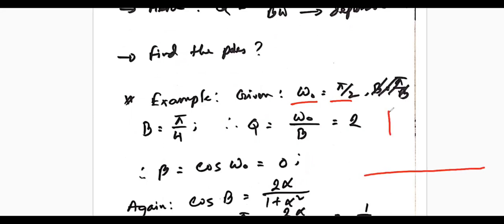So if we draw the frequency spectrum, the magnitude response plot, we have 0 here and we have pi there. And if this is pi by 2 and this is your omega 0, that means this is the center frequency. The center frequency should have the maximum amplitude, 1.